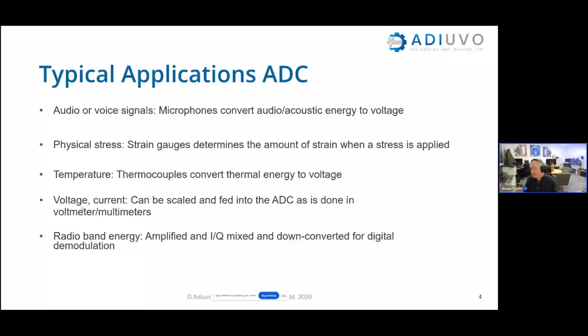So when we come to look at our ADC application later on, we're going to be using a negative temperature coefficient thermistor with a little RC network, and we're going to use that and the XADC to convert the resistance that's measured, actually the ADC count that's measured, and go through a processing chain to convert that into a temperature. Obviously, we can use them for telemetry as well to measure our voltages and currents, and that's really simple with those XADCs, because we can just read that data directly. It's available to us directly over the AXI bus or the DRP bus.